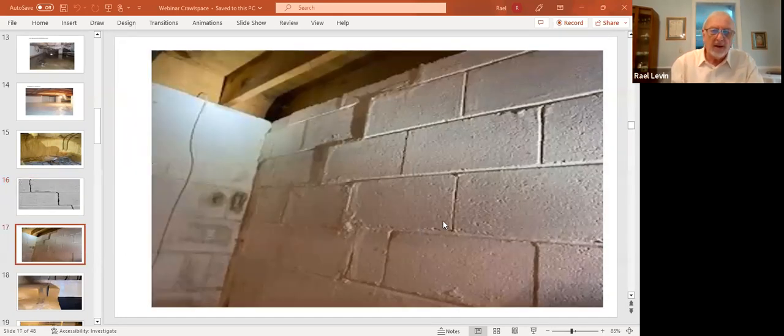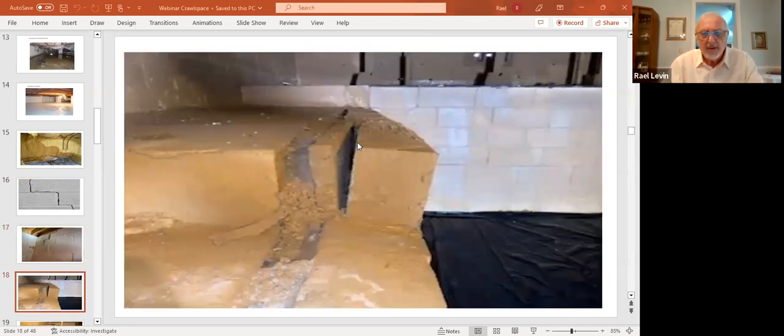And of course, the same with this situation right here. Well, here you can see where some concrete is actually being poured in. There's the original cement block. You can see they've got some supports back here. So we've had some settling here for a while, and now they've put in other walls here. There's an actual crack in this back wall, so the hydrostatic pressure is still working there. We've had some of these walls actually pushed away. So you realize by looking at this that the hydrostatic pressure is pretty strong.